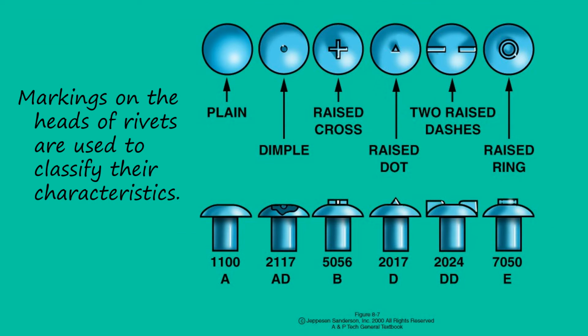You should memorize these rivet alloy numbers and corresponding 1 or 2 letter alloy identifiers, and the rivet head markings they correspond to for quiz purposes.